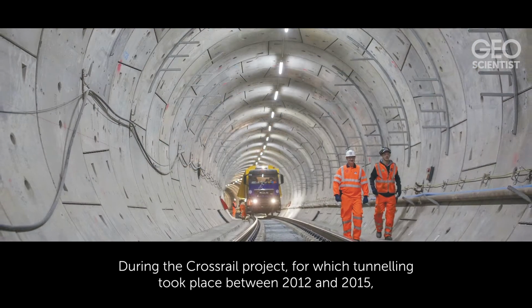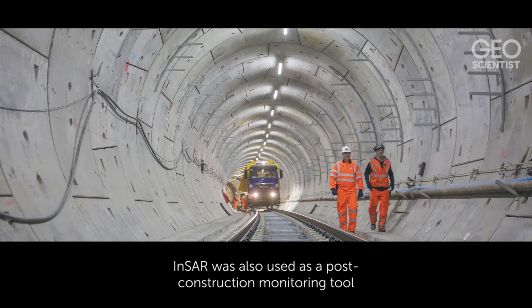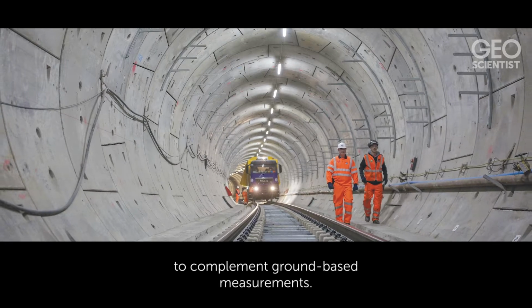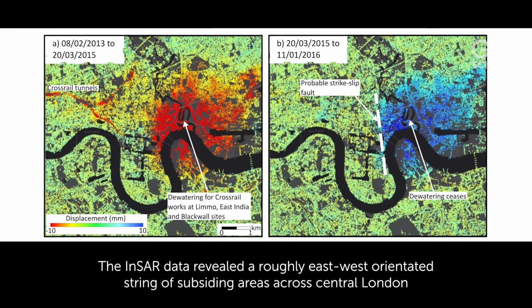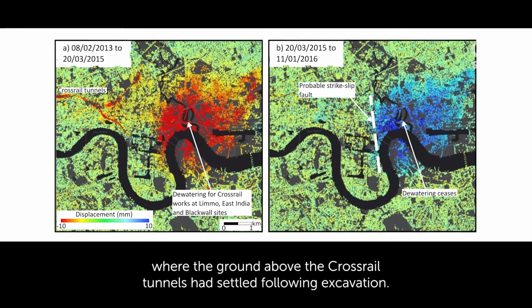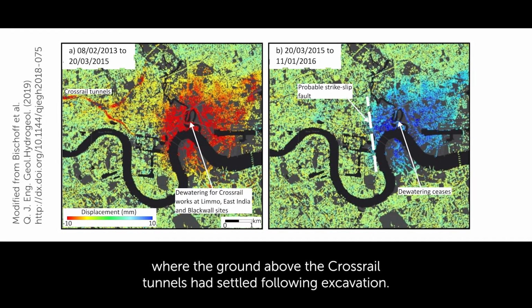During the Crossrail project, for which tunnelling took place between 2012 and 2015, InSAR was also used as a post-construction monitoring tool to complement ground-based measurements. The InSAR data revealed a roughly east-west orientated string of subsiding areas across central London, where the ground above the Crossrail tunnels had settled following excavation.